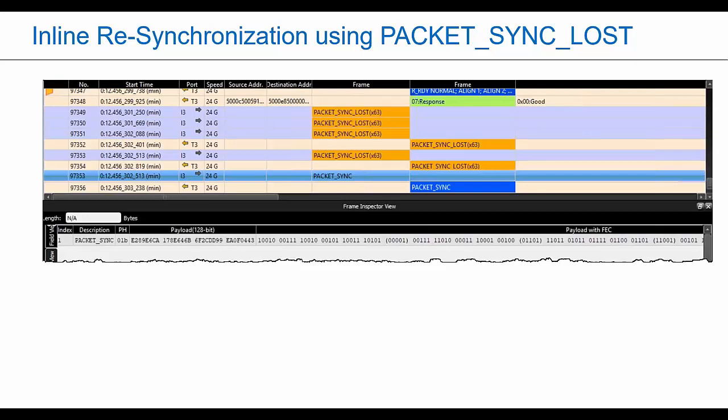There can't be an active connection open when starting this sequence, but when the PHY receives a packet sync loss now, he needs to basically send the same. And then once 2 consecutive packet sync loss primitives are detected by his receiver with no decode failure, then he can transition to sending packet sync.